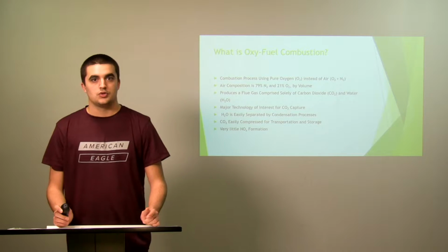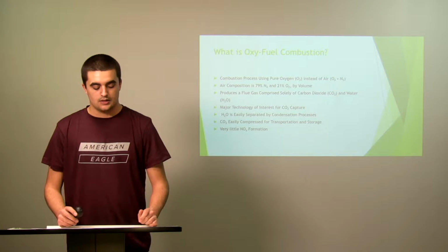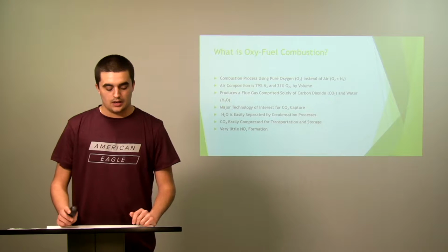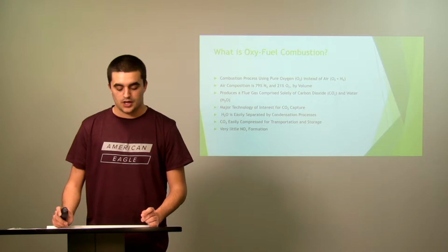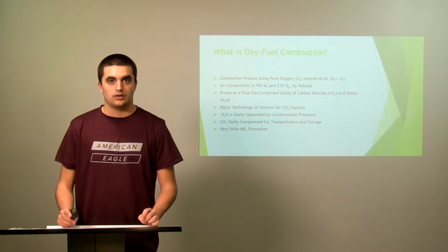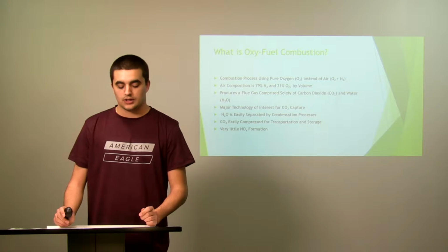This is mainly due to the flue gas only being made of water and carbon dioxide. The water can be easily separated through condensation processes, and the carbon dioxide can easily be compressed for further transportation and storage. Another benefit of not using air is there's very little NOx formation, with very little presence of nitrogen within the combustion process.